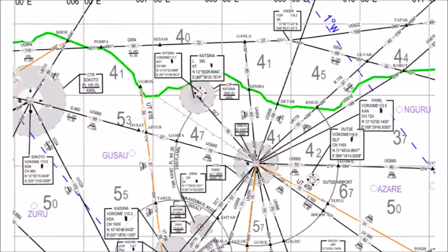The first step in navigation is deciding where one wishes to go. A private pilot planning a flight under VFR will usually use an aeronautical chart of the area which is published specifically for the use of pilots. This map will depict controlled airspace, radio navigation aids, and airfields prominently, as well as hazards to flying such as mountains, tall radio masts, etc. It also includes sufficient ground detail, towns, roads, wooded areas, to aid visual navigation.